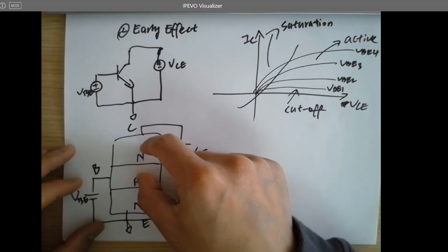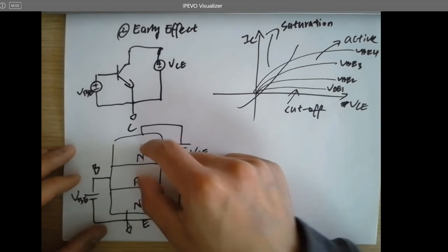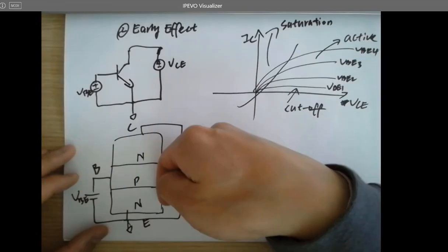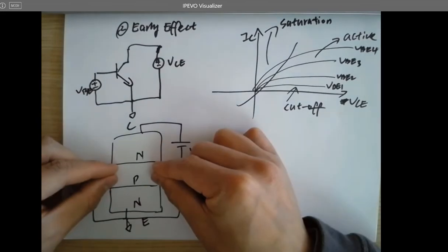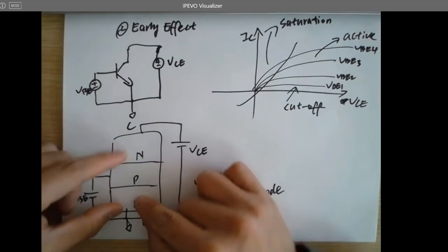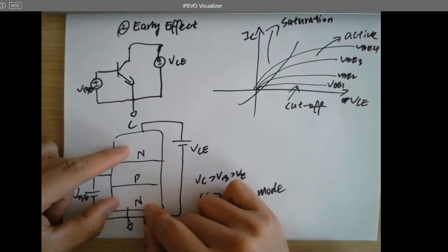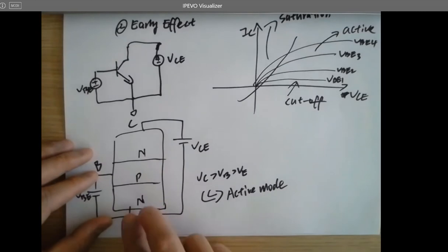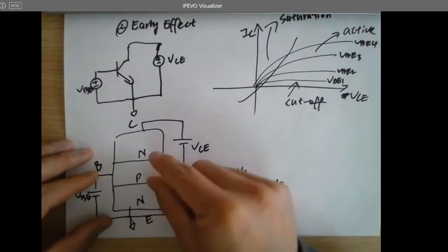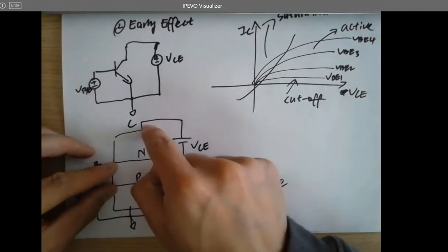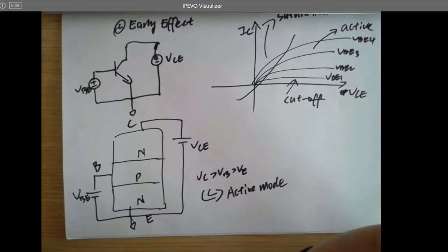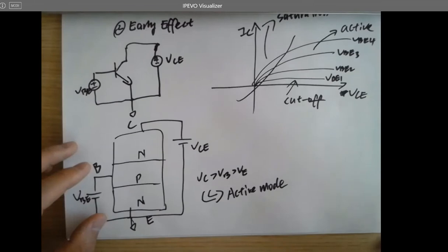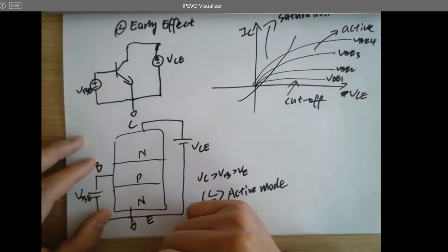All right, that sounds weird, right? Reverse bias, how can I inject the current in that direction? Because the base is super thin, very, very thin, and the emitter is heavily doped. So the electrons can be swept through this very thin layer and arrive at the collector. Is that making sense? That's why it's called collector. It's collecting electrons. Emitter is emitting electrons upwards.